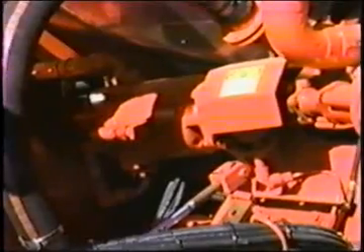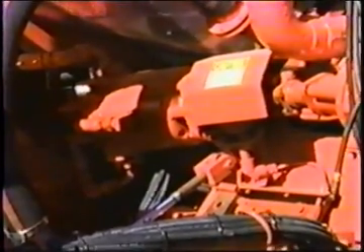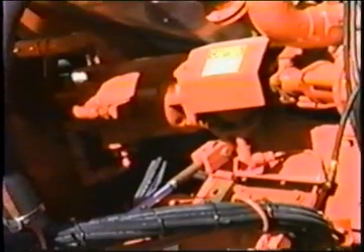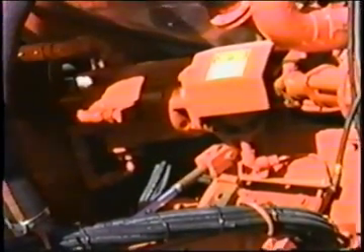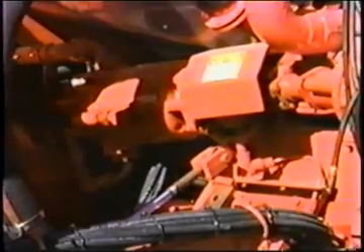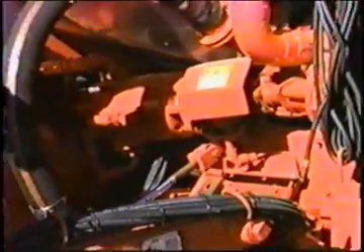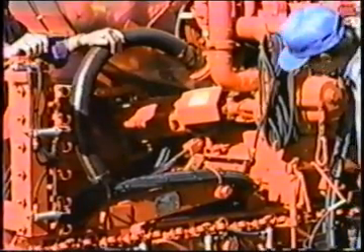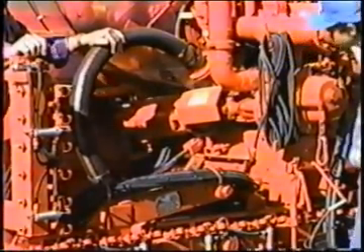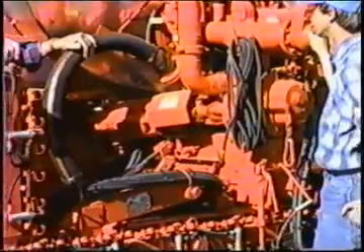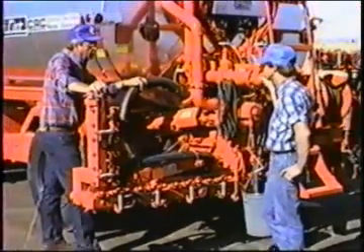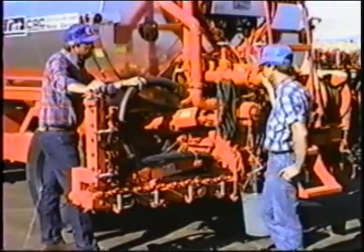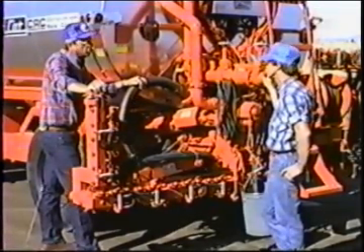Now they're actually seeing just the speed, but the computer, the electronics, convert that speed into gallons per minute. That math is already done for you. There are 3 numbers that determine the spread rate that the machine is putting down: the gallons per minute that we're pumping, the width of the spray bar, and of course the travel speed of the pump. I'm sorry, the travel speed of the truck.